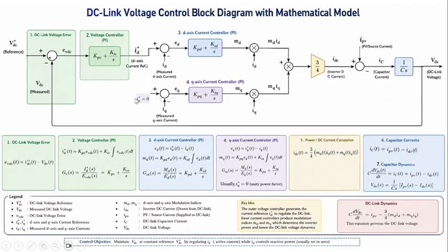We are not intended to control the reactive power. If you want to do power flow control, in that case how much active and reactive power we need to pump into the grid, or we need to draw reactive power from the grid, in that case we have to give some IQ star. But as of now we are just generating the PV power and feeding it to the grid. For that case, this is the control strategy.